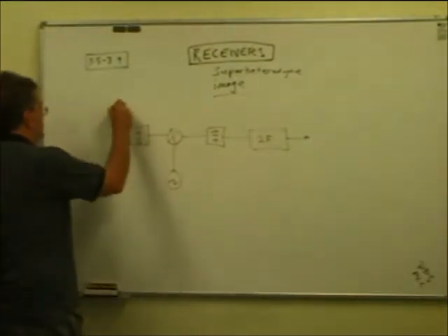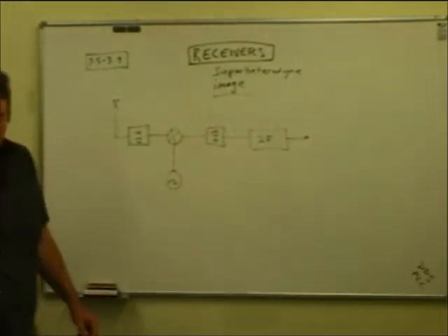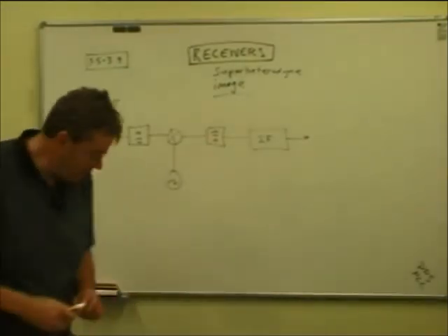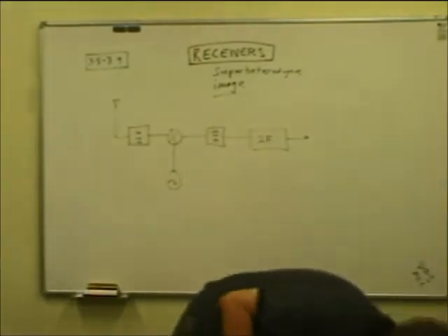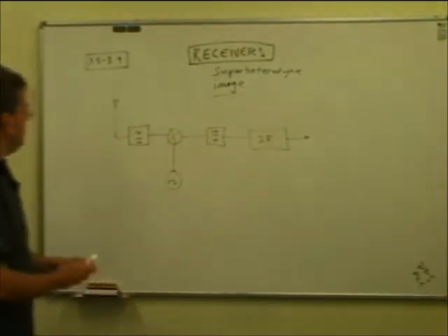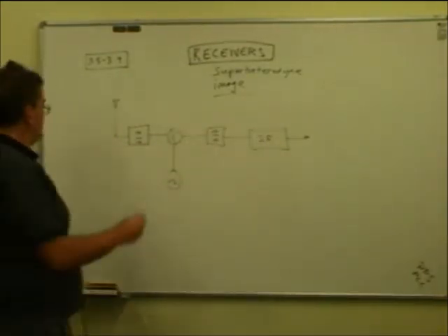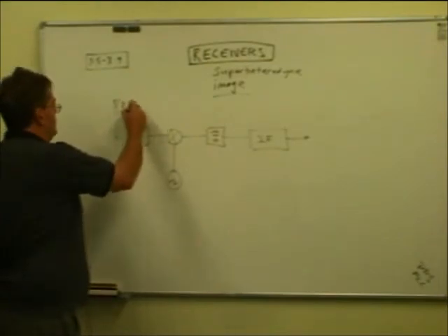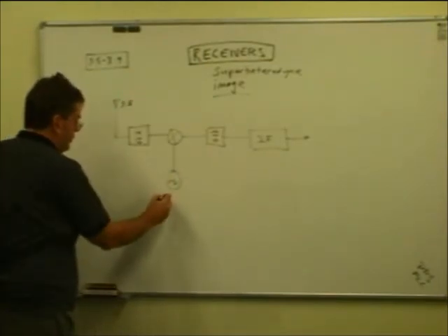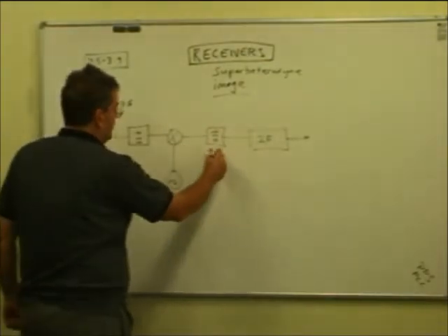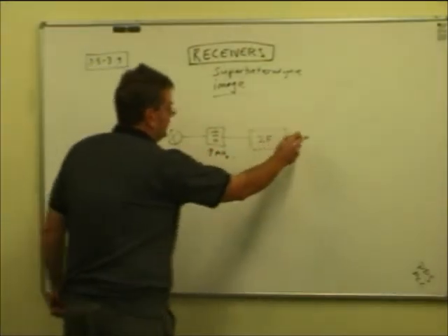What we now need to talk about is how we receive single sideband. That's where things get a little bit more complicated. The front end arrangement is still the same. We still have, if we want to receive 3.5 megahertz, the local oscillator running at 5.5, the mixer, crystal filter here at 9 megahertz, IF, and so on.